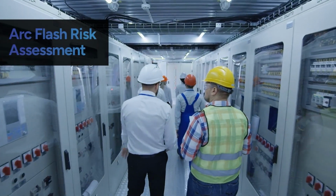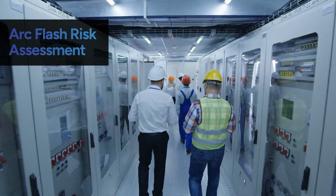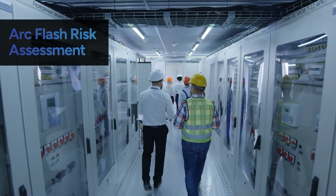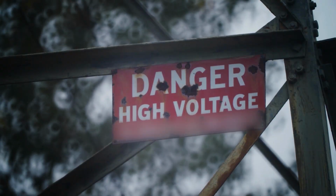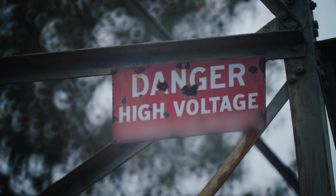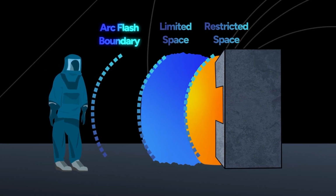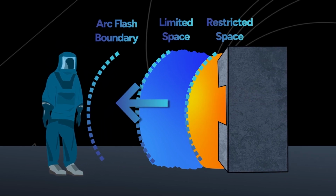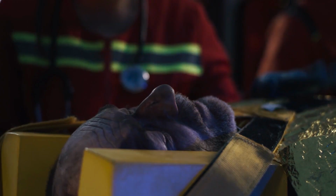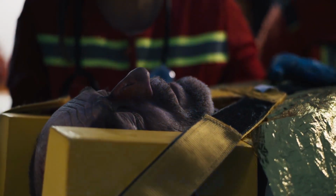Now focusing back on arc flash. The arc flash risk assessment specifically focuses on identifying the likelihood, severity, and range of an arc flash. This helps us establish safe working distances and the level of protective gear that we need to wear. From this assessment, we could add a third approach boundary, the arc flash boundary. The arc flash boundary marks the distance where a person could still get a second-degree burn if an arc flash occurs. Now, a second-degree burn is treatable, but it's still not ideal, so more distance is always better.